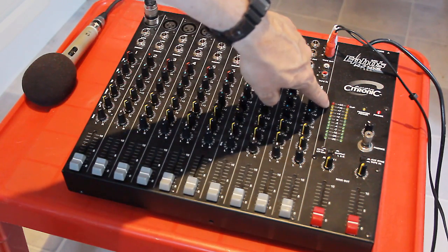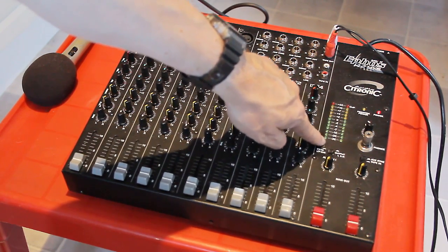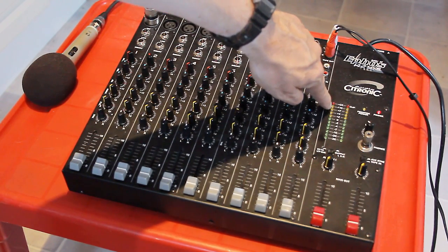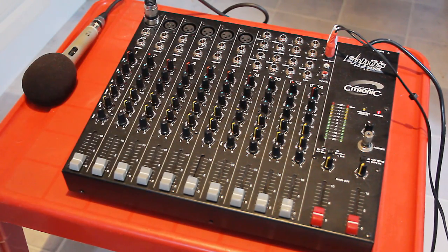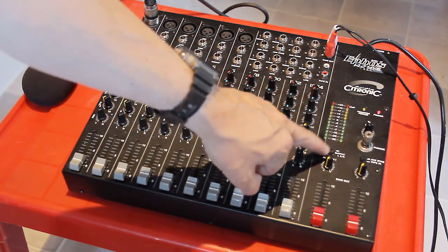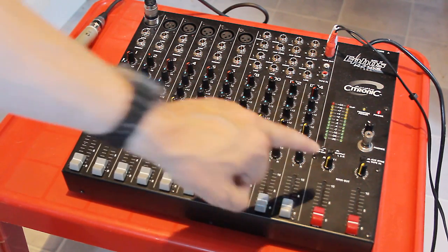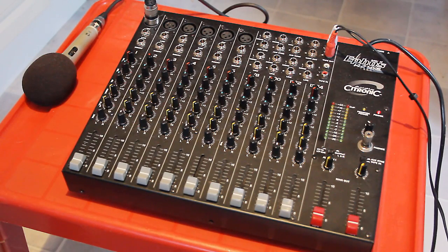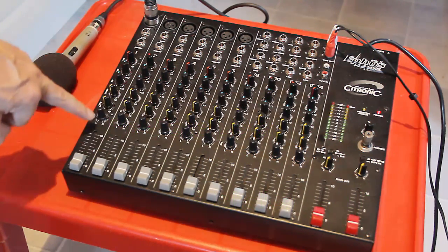Ordinarily, the level meter shows the overall output of the mixer, but if we engage this Q switch here, then the left-hand column of LEDs shows the input level of the channel or channels being tested. This mixer is a bit atypical in that it only has the one Q switch. Most mixers have a separate Q switch for each input channel, and it's often labelled PFL rather than Q, with PFL standing for pre-fade listen, which refers to the fact that it allows monitoring of the incoming signal before its arrival at the fader.